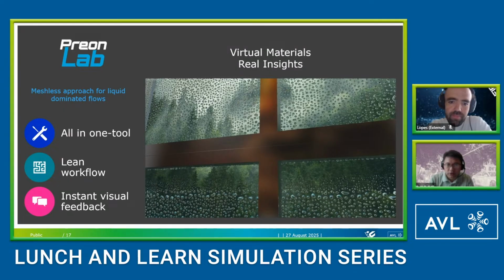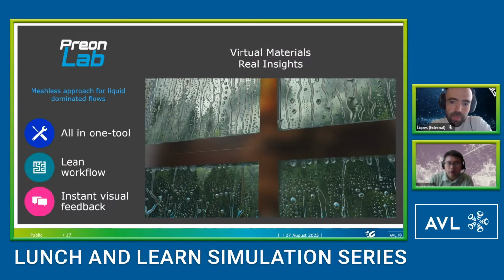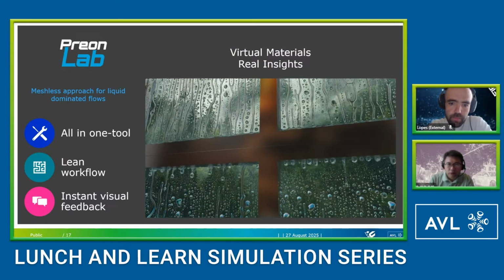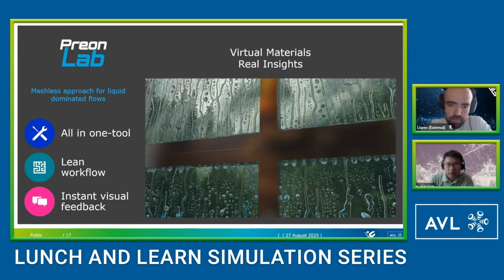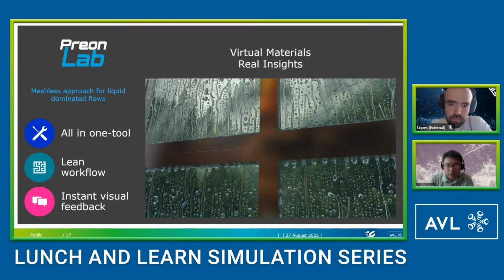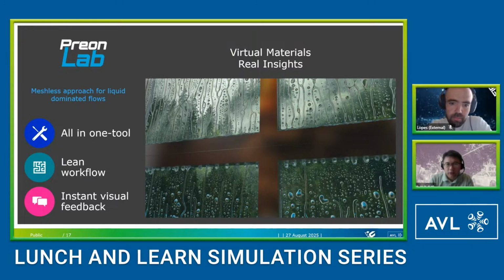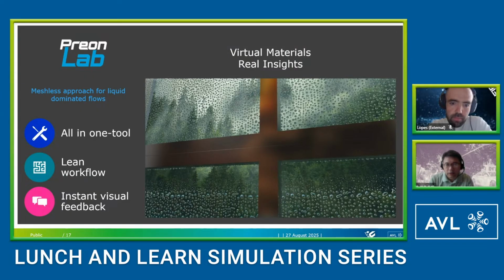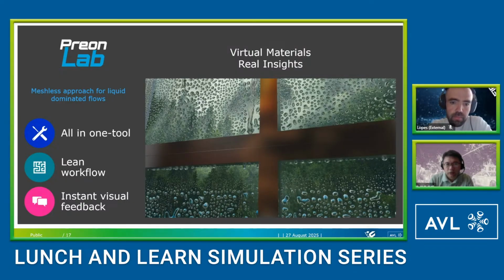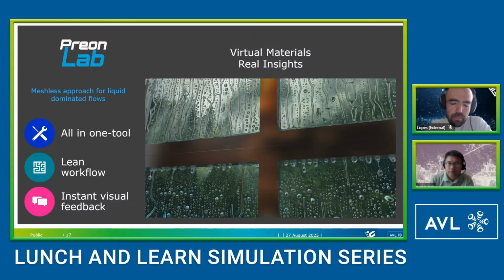With the rain droplets on the window panel, the small droplets will stay there, and as they grow bigger, they start to flow down. Gravity overcomes the surface tension, so we have a good adhesion model. We call it the lateral adhesion model, to deal with the dynamic contact angle of this water here.